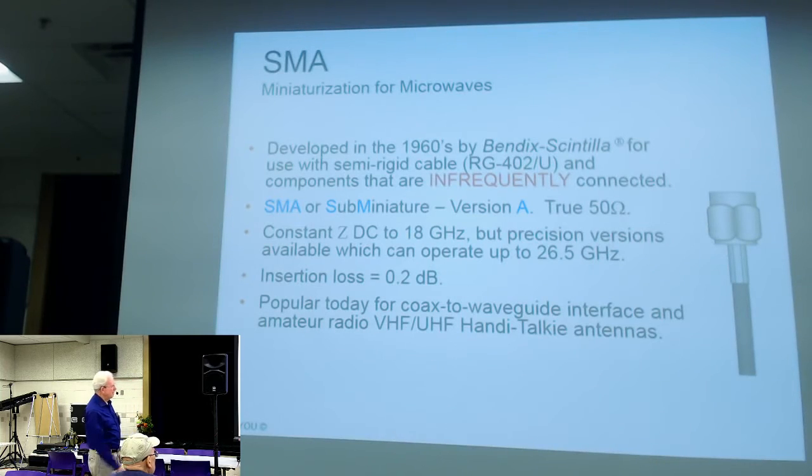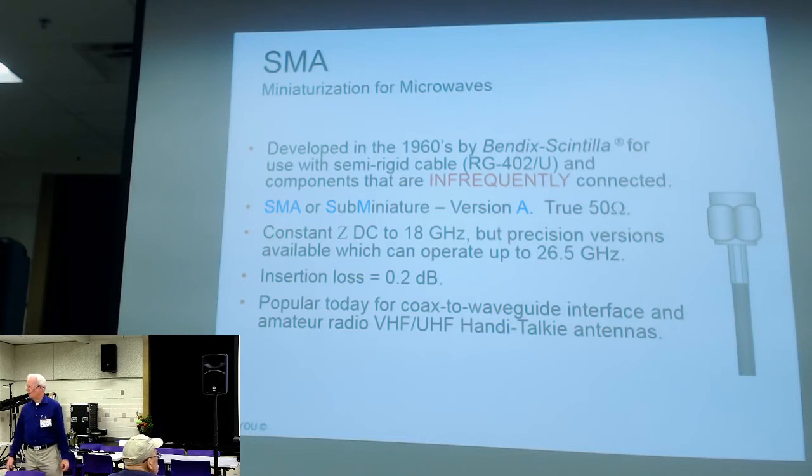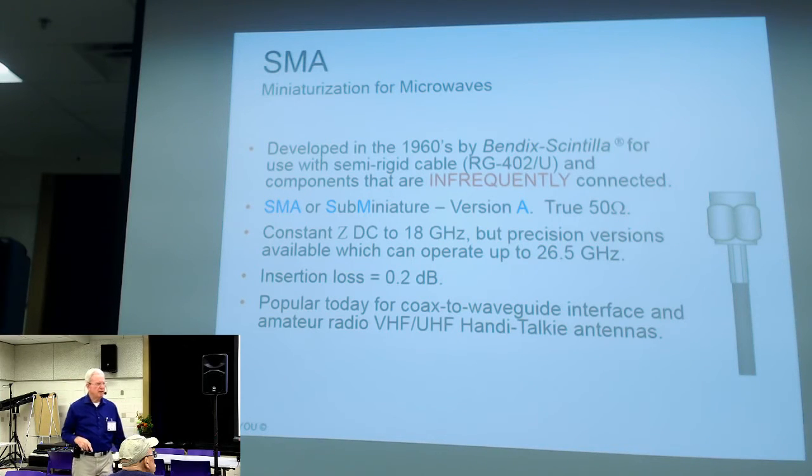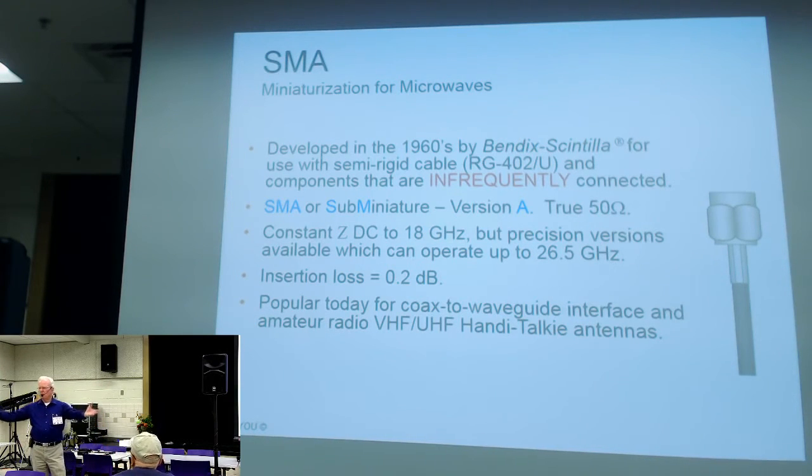Very popular for your Baofeng and your Wouxun walkie-talkies. They use these. And here's the problem with your walkie-talkies, guys. I know a lot of you have your Wouxuns out here today. They put a male connector on the radio. So what happens is every time you twist the antenna, which has a female, you're rubbing the male pin, and one of these days you won't have contact at all. You're just wearing it down every time. It's just getting worse and worse.